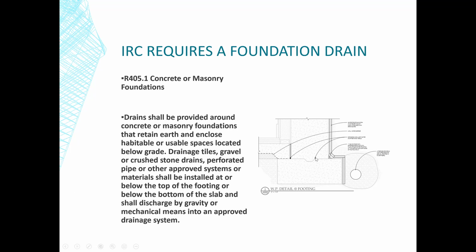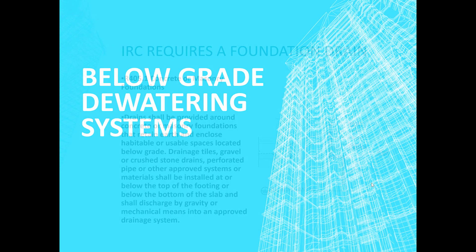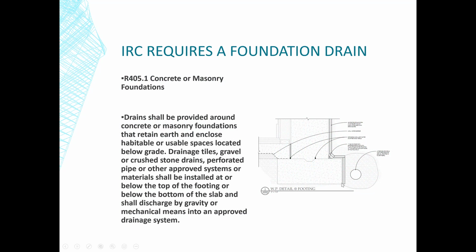We've got a footing, foundation. Before we backfill, we've got to get this waterproofing all on. We've got to get the drainage mat on. First thing down, we put. Now, some people don't put the Mirafi down below. I think that this is a better diagram for what I would like to see: Mirafi wrap that, or the fabric wrap the entire thing. So put the fabric down, put some gravel down to here, put the pipe in. So the fabric would be hanging up over here on the excavation, kind of like up that way.